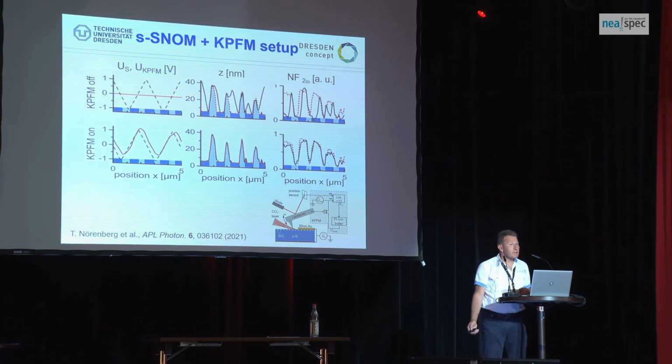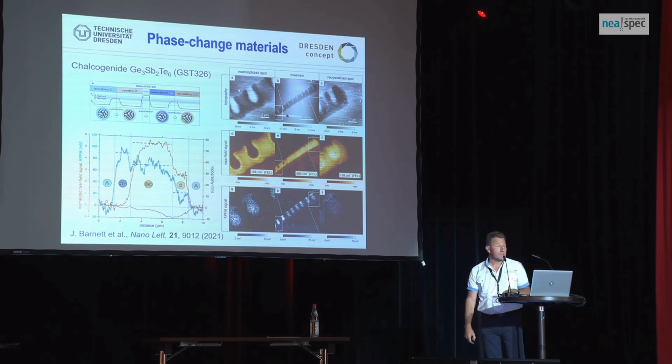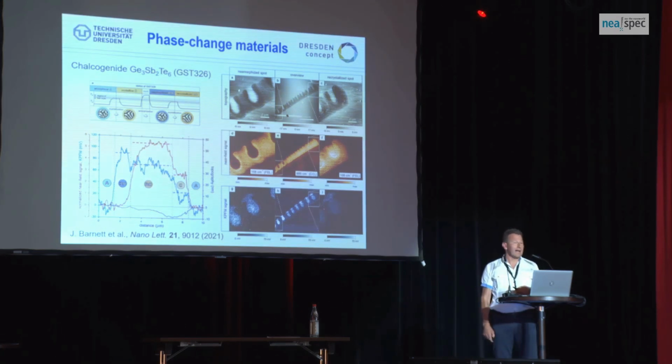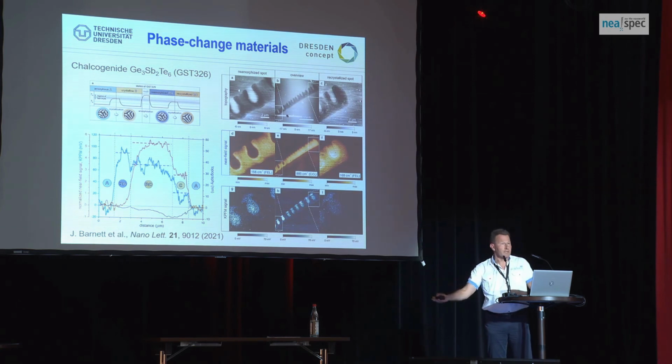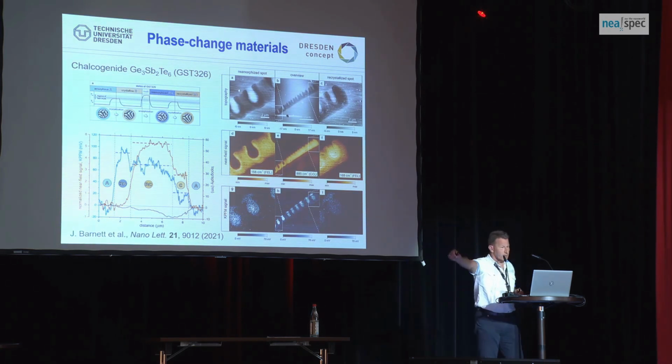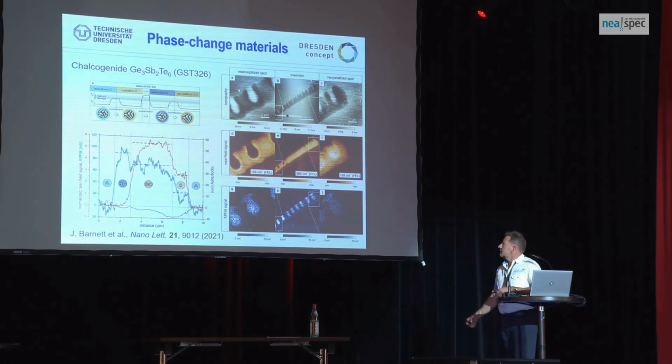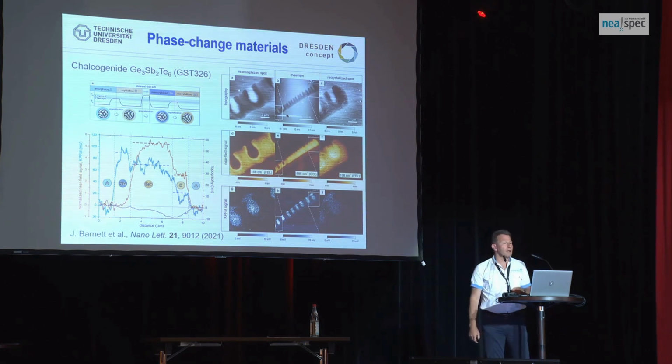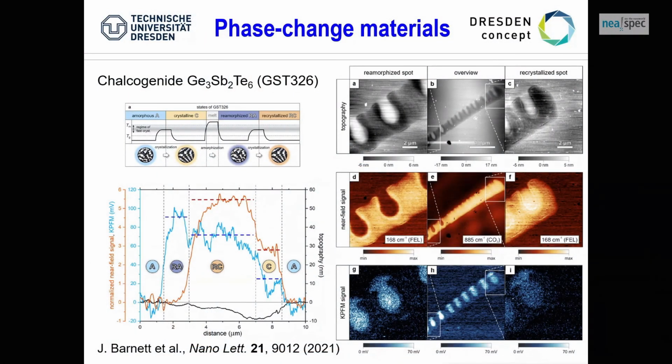Let's go for imaging. This brings us a new thing, which means that now we can also take the additional Kelvin information that we have been measuring. We have 3 channels here: topography, the near field, and on top of that, we have this for free, the Kelvin potential. We take the output of the PI, put this into a channel, and what you see nicely is really imaging exactly. You see different colors, which means bright and dark for different crystallized areas. Taking cross sections, we see that we have 4 different regions.